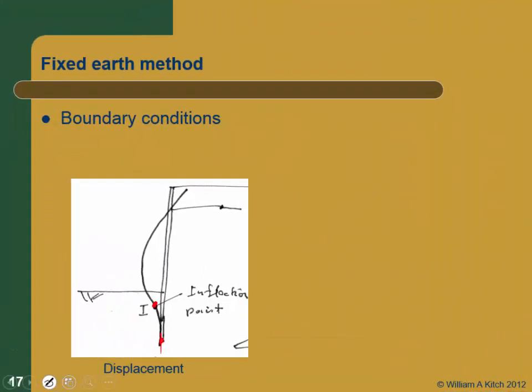Okay, and for you structural engineers, what do we know about the inflection point? If this is a beam and we have an inflection point there, what do we know about it? We're getting a change in curvature, so that means that's a point of what? Anybody awake today? Your beam was smiling. It went from smiling to frowning, so what happened? Zero moment at the inflection point, right? Has to be. See, that wasn't so painful, was it?